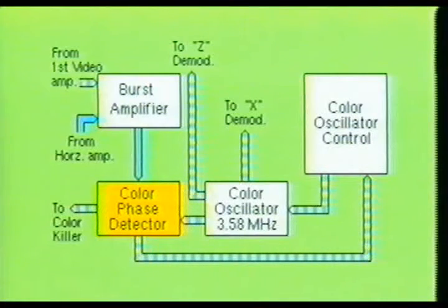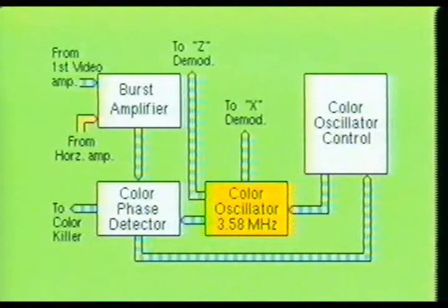and the chroma bandpass amplifier remains activated. The primary function of the color oscillator stage is to provide the 3.579545 MHz signal, which is used as a phase reference to demodulate the chroma sidebands. This stage actually restores the subcarrier that was suppressed at the transmitter.